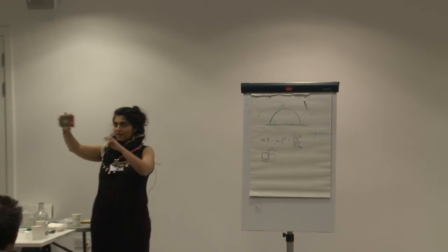These electrodes each have a mini transistor underneath, through hole. The transistors are controlled by an Arduino, connected to a power supply that takes 12 volts from a regular power supply and steps it up to 260 volts. It's adjustable, so you can adjust it with a potentiometer for each application that you use.